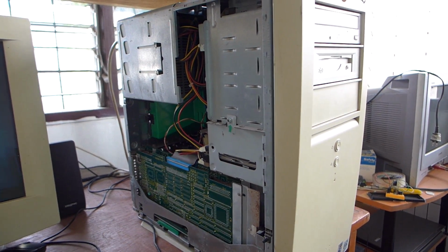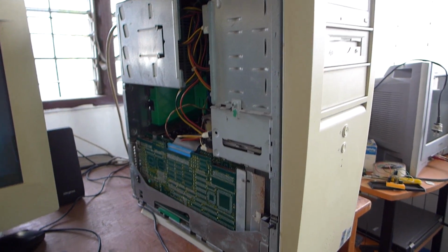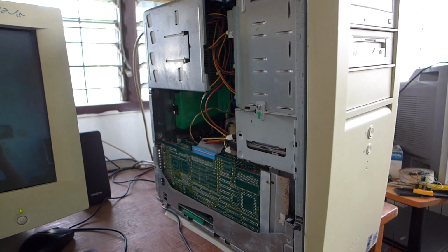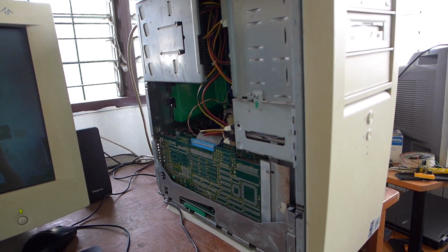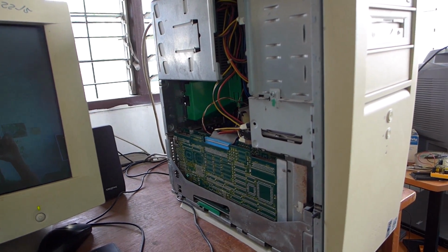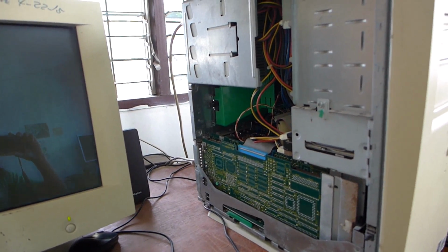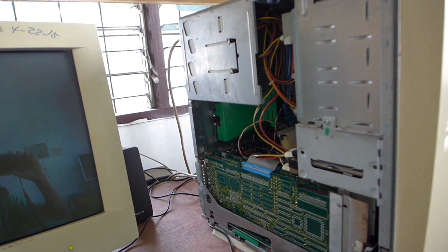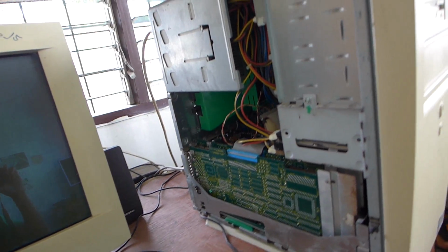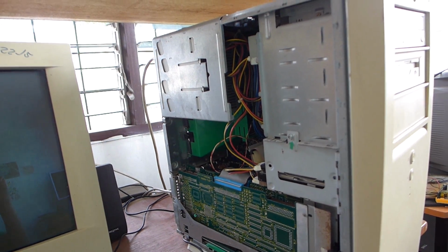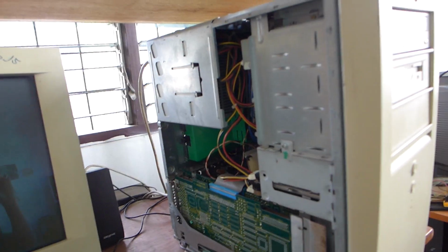I also need to mention that the video output quality will vary on the DTL-H2000 depending on the quality of your computer's power supply. If it's a very cheap power supply, then expect to see fuzzy noise that scrolls up the screen and then loops back. But if you have a relatively high quality power supply, like in this Dell, it should be mostly noise free.